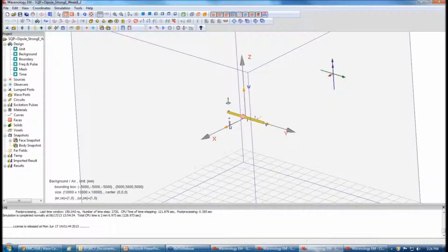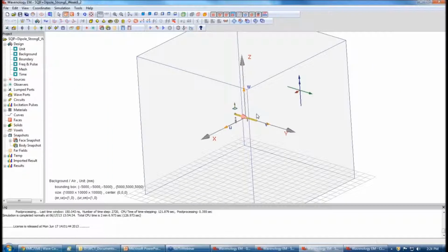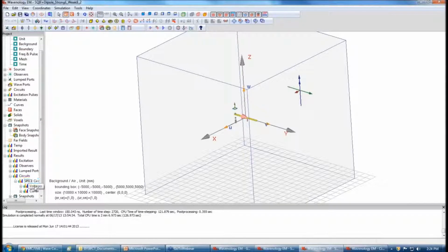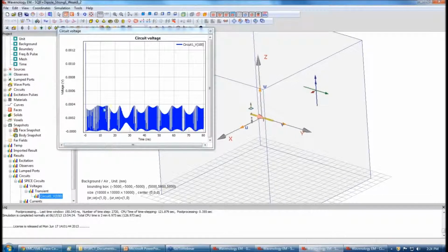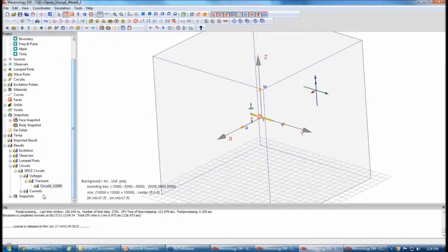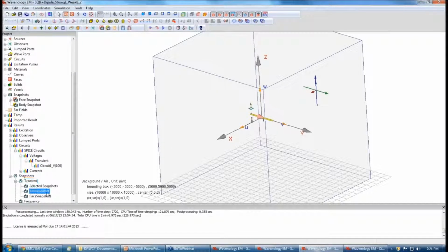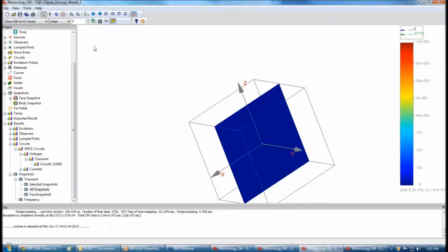Very simple. Remember, in the slides, I showed you the vertically placed dipole antenna. But in this case, let me just make it parallel to the y direction. And you will see that the circuit is definitely being interfered with if you make the dipole antenna this way. So you can see the response is totally different. And you can also see in 3D how this field is propagating and interfering with each other. Okay. So let me plot that out. You will see the field coming in is radiating out and it's interfering with that device.